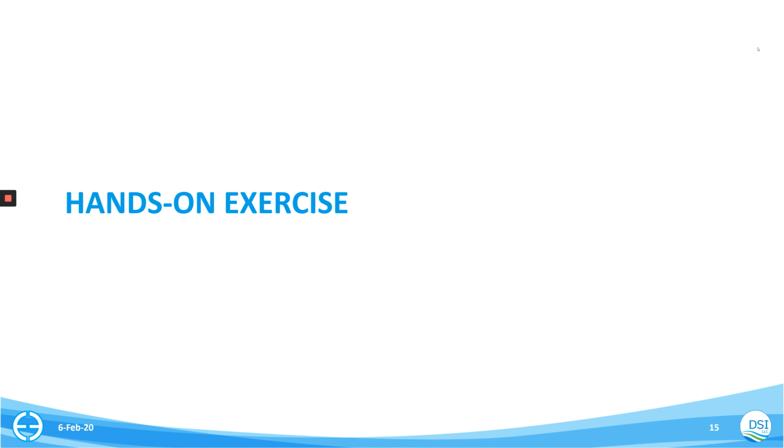Say you have a pretty fast model and you want to do some long-term simulations, say you're going to predict that the sea level will rise 20 centimeters over the course of 10 years. You could just apply a simple linear relationship to your existing data and say, okay, the next 10 years are going to look like the previous 10 years, except by the end, we're going to be on average 20 centimeters higher. And you can just apply that to your open boundary condition and run that simulation.